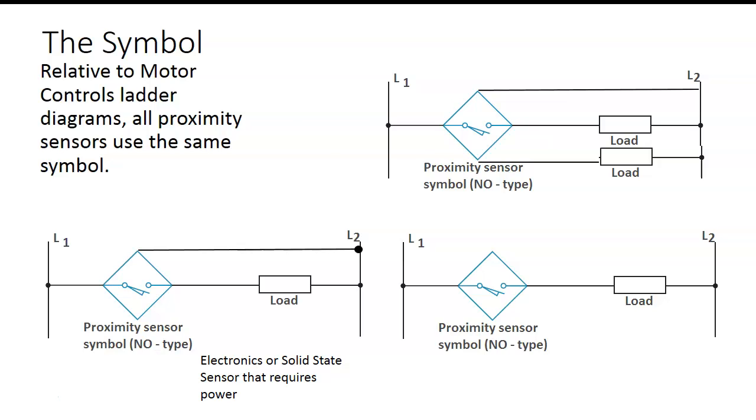So this would be a 2-wire sensor. The sensor actually powers up through the load, so these are going to drop a voltage across them. Here we're going to measure probably around 4 to 6 volts across this, because they have to create power, right? You understand? So they have to drop a voltage.